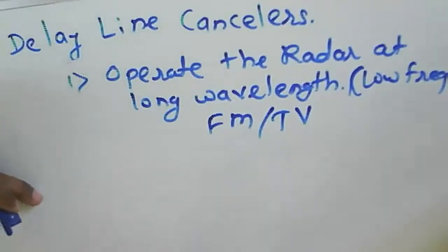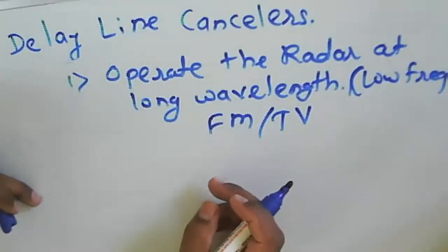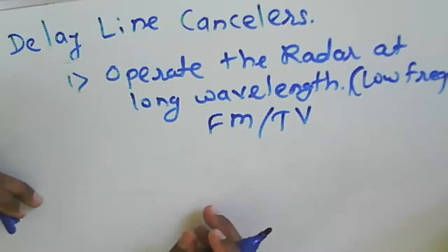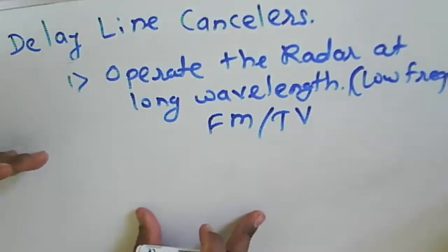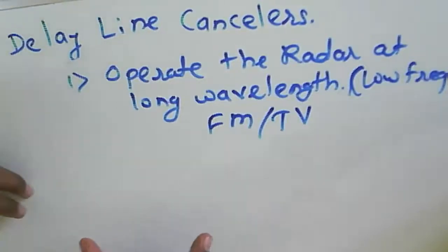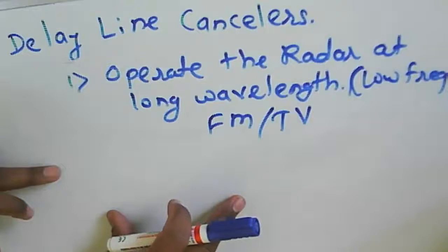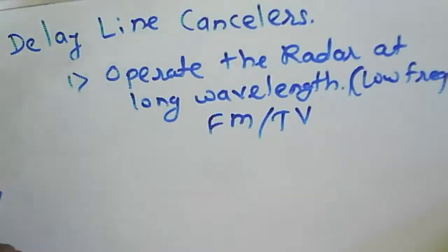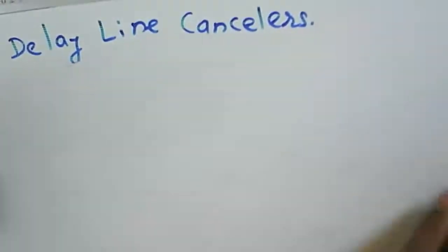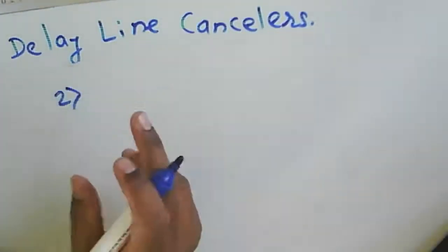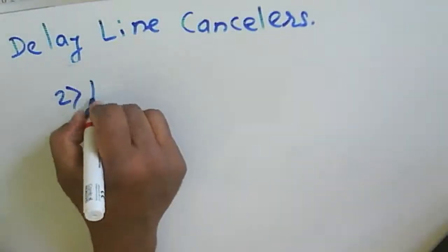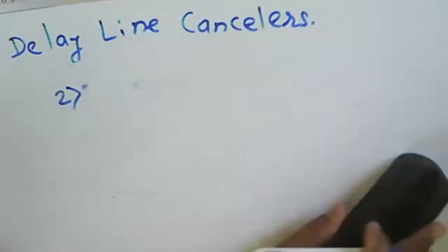Again, we use the same VHF frequency band for air surveillance. This frequency has low altitude coverage, and that coverage is generally poor. So attempting to use low frequencies to avoid a blind speed again creates a problem for the radar in this specific band, because it is a crowded one. Another case is that we can use a high frequency signal instead of the low frequency.